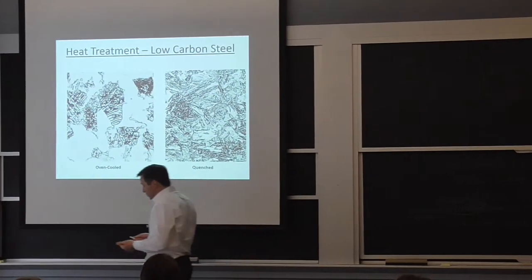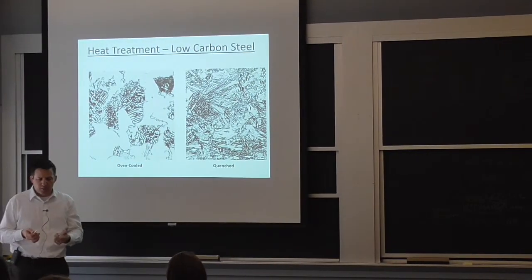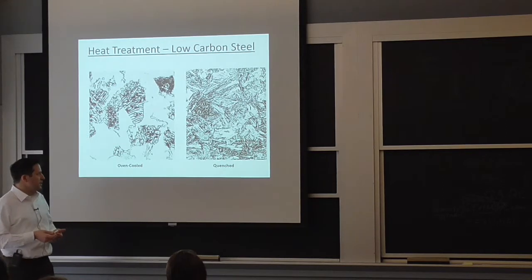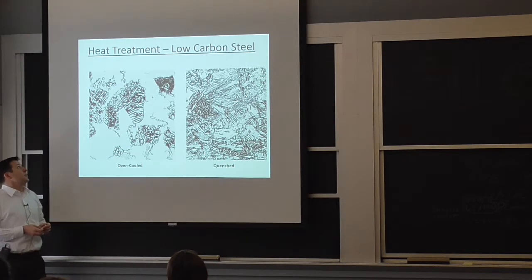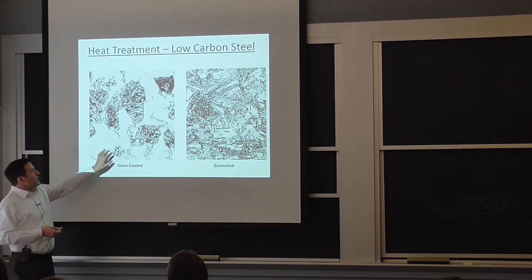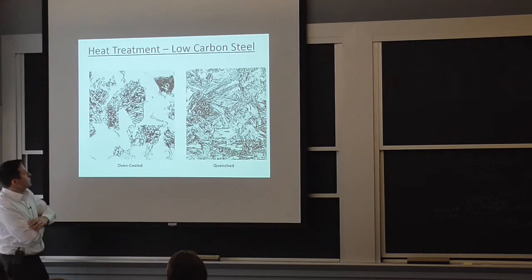In terms of our casting process, we had the problem of chemistry. We said we're going to keep it hot, deform it, and that's going to fix the grains at the same time. There is an extra process that's heat treatment that you do to a lot of alloys to tailor their microstructures. So in this case here, it's the case of steel that was just cooled fairly slowly. What you can see, it's a fairly coarse microstructure.